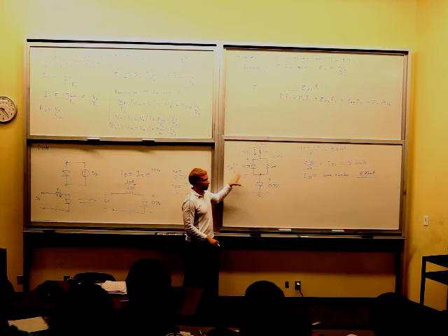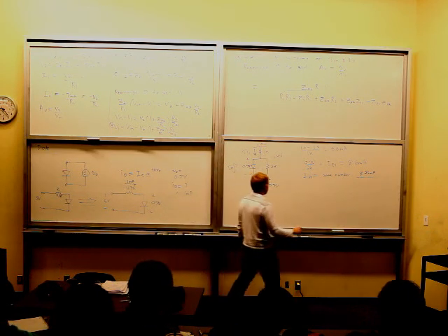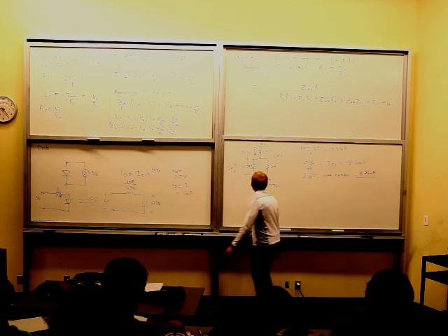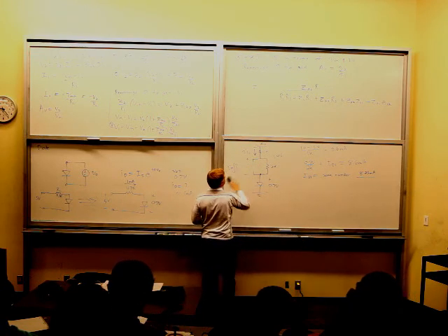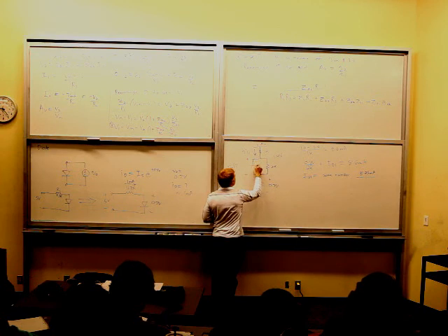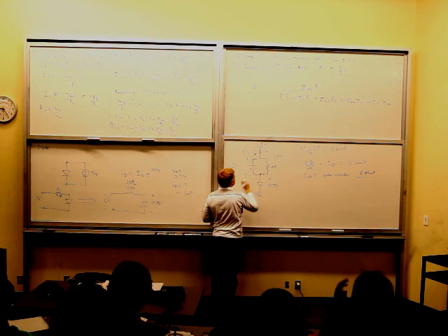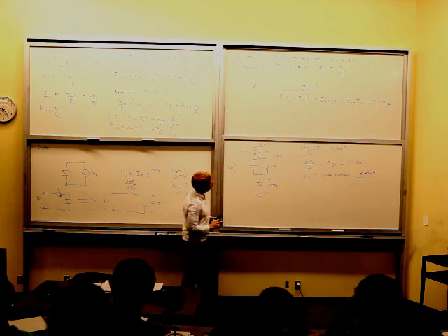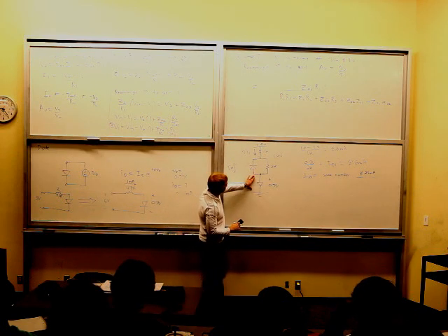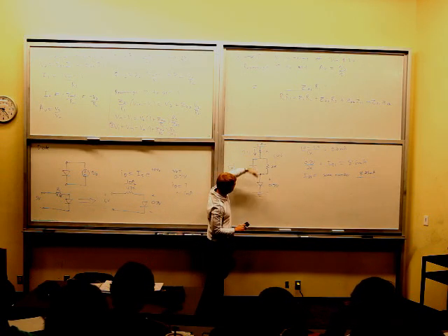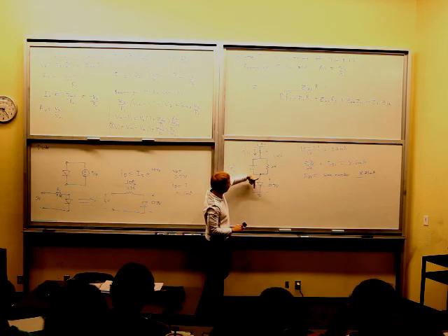I just assume that things are forward biased. Now, if you see something that's obviously wrong, like here, let's say that this diode was facing the other way. What I would do is I would say, okay, yes, this one's going to be forward biased because we have positive voltage and ground, so current's going to want to go through this way.